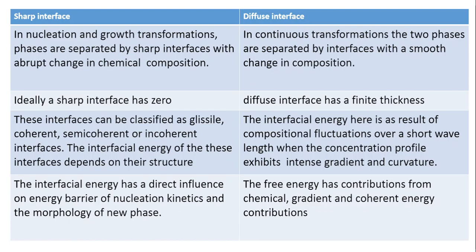The interfacial energy of a diffuse interface is the result of compositional fluctuations over a short wavelength when the concentration profile exhibits intense gradient and curvature. The interfacial energy has a direct influence on the energy barrier of nucleation and growth type of kinetics and on the morphology of the new phase.